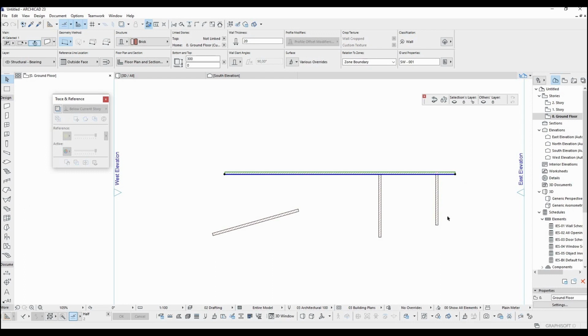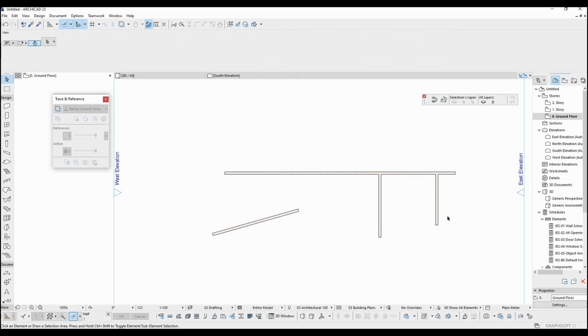I'm going to show you how to trim anything as well as walls. You just press the Ctrl button and click any item you want to trim. You can click any part of the wall, the end of the wall, between any two walls, or this kind of walls.